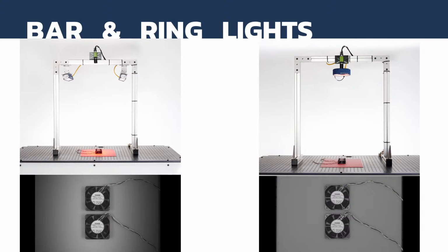The fan itself, that bright label is silver and somewhat glossy. The plastic, though it's black, has some texture and some gloss to it as well. Both of these need controlled lighting, either a bar light or a ring light, to get a very good flat image. If we just use the ambient lighting or light that's around in the room, there would be angles between that light and the camera which captured glare, and parts of the image might not be as good even if it generally were working. And more than that, you'd be subject to changes in that room lighting.